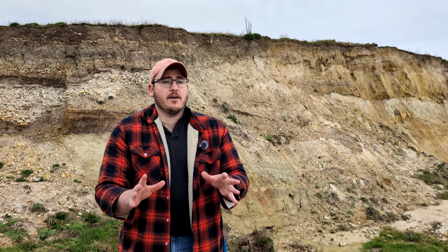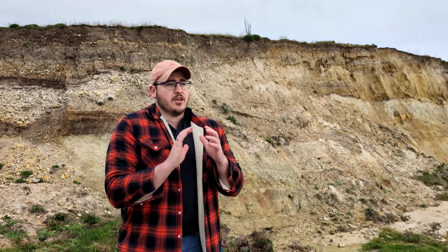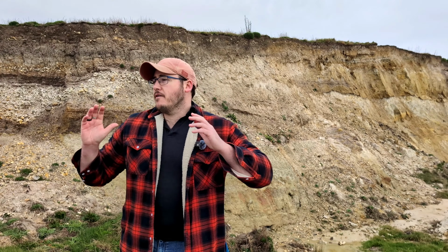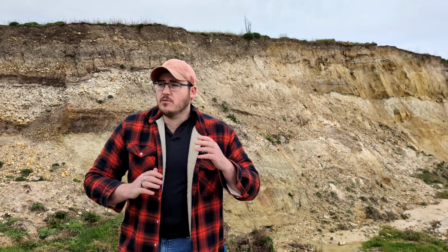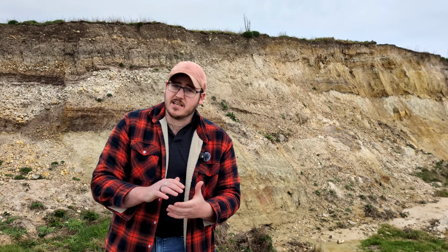And that comes from experience. But the important thing when you are flying it like that and flying manually is to at least have an observer with you. You want to be a responsible drone pilot. All too often I've seen cowboy drone pilots who don't really care, and don't look into your airspace restrictions, don't look into knowing that for certain types of drones, particularly like this one, you want to be registered. In my case, I've got both a GVC and an A2,